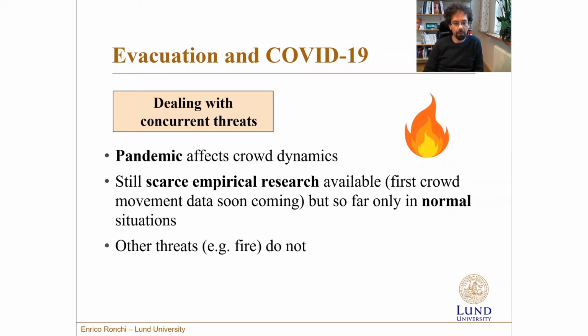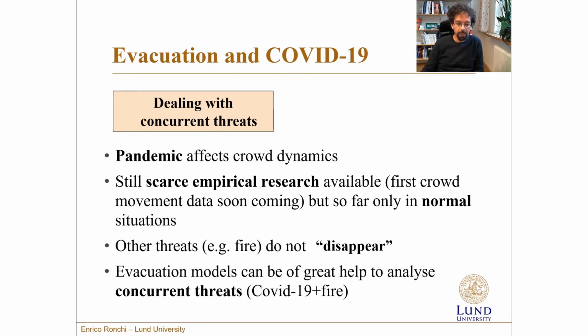And the problem is that it's not that since we are in a situation in which we have COVID-19, all other threats, for example the fire, disappear, as I made it disappear here. The other threats are still present, so we will have to do a design, for instance our fire safety engineering design, but take into account the consequences that the pandemic might have on the crowd dynamics, as well as the possible risk linked to the exposure of the occupants to the coronavirus.